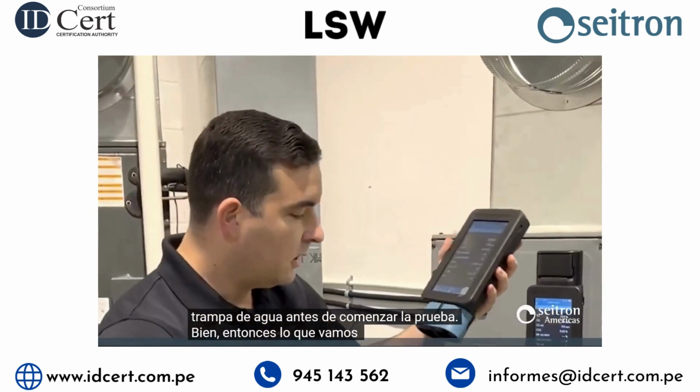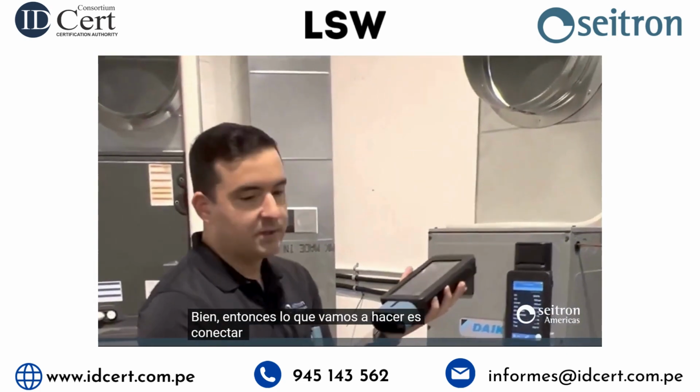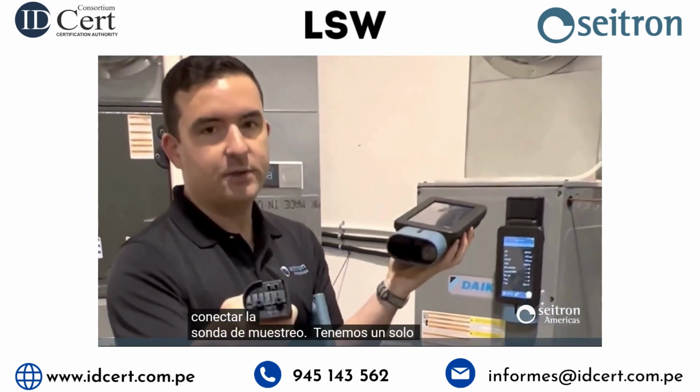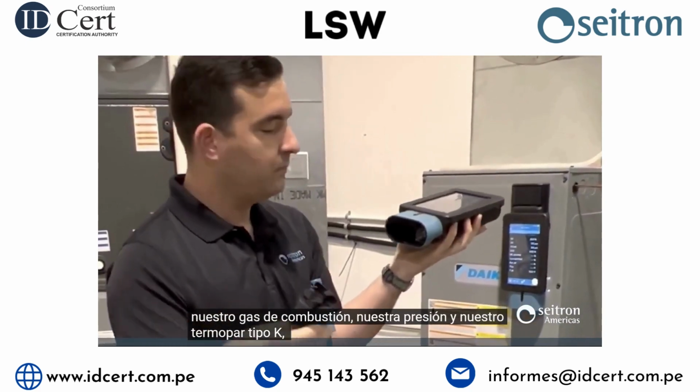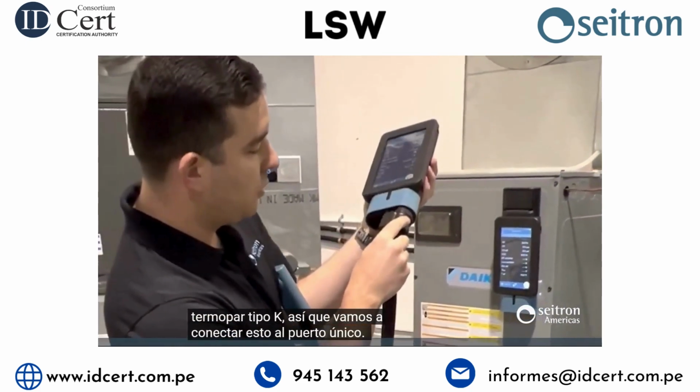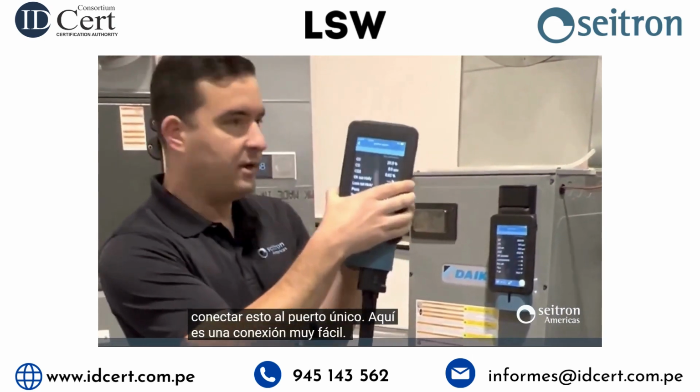All right. Then what we're going to do is connect the sampling probe. So we have a single connector with our flue gas, our pressure, as well as our type K thermocouple. So we're going to plug this into the single port here. It's a very easy connection. Now we're ready to go.